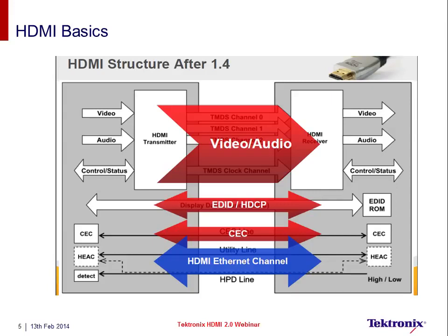These are the four lanes which are termed the high-speed lanes of HDMI interface. The relationship between the clock and the data is in the ratio of 1:10. That means for a maximum data rate of 3.4 gigabit, the clock rate will be 165 megahertz.